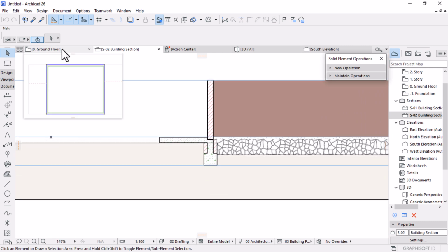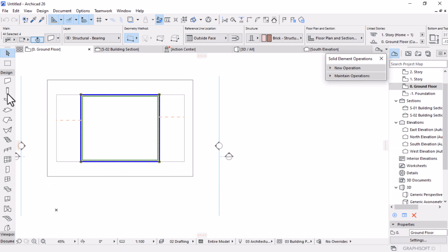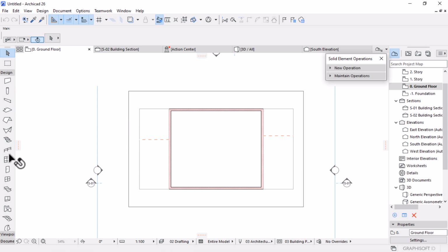Okay, so I'm going to go here underground, then I will activate the roof tool. It's always good to understand how these native or primitive tools can be used out of their context. In this case, I could use the terrain tool, but with the terrain tool, I need to have two layers here. So I would have to use solid element operation to stack two layers of terrain and then trim it, because the terrain is fine, I can reduce its height. Okay, let me just show you instead of explaining.